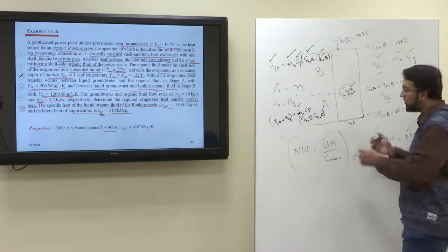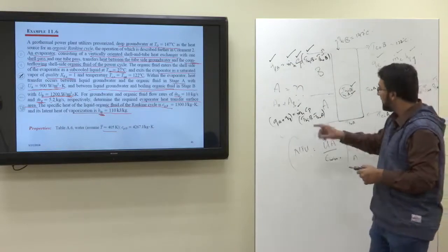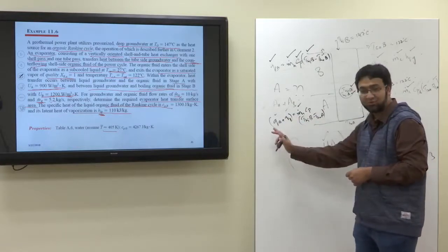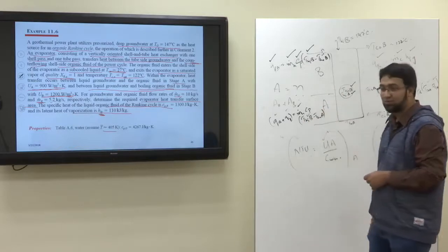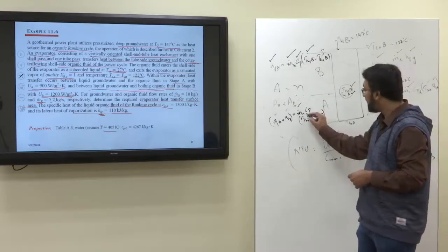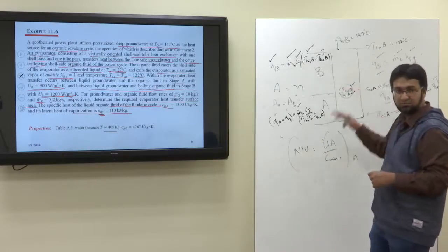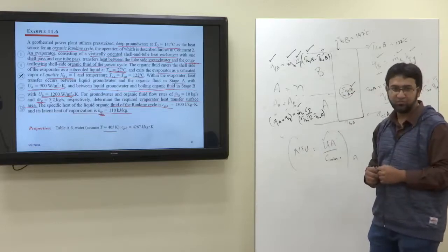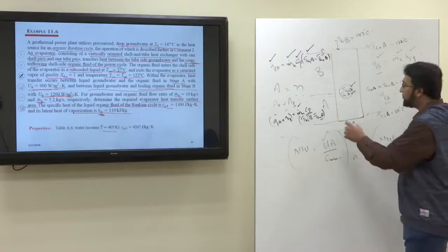Okay, Q will be the same for hot and cold. So m dot h we know, QA and QB we know, these are all exact values we know. T hot inlet B, this is also an exact value we know. Okay, Cp is our assumption, and they took the assumption already at the mean of the whole heat exchanger, the combination of two. Okay, so this will be more accurate compared to if you just use QB.